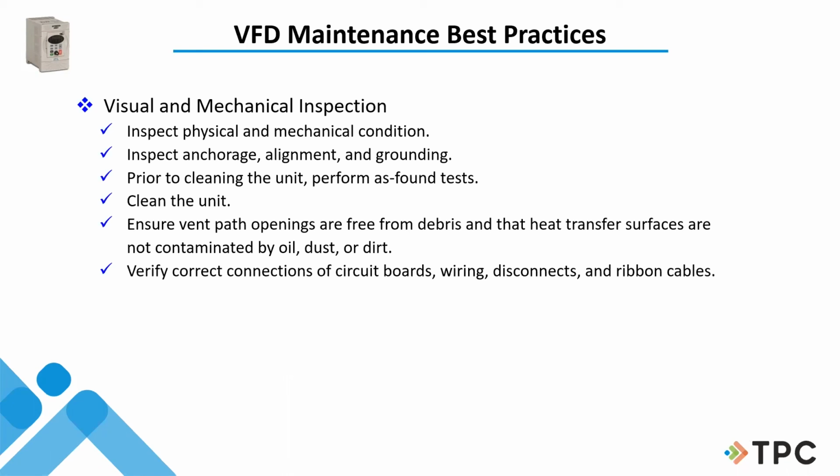Back to some visual mechanical inspection, of whatever it's on. And it talks about alignment and grounding. Grounding conductors get very little preventive maintenance. Cleaning the unit, cleaning filters, cleaning the little muffin fans on the bottom of your drive, all of those things are going to get dirty. Even if you're in a clean room, they're going to get dust and dirt on them. And you need to make sure that you clean them, maybe twice a year, depending on your environment.